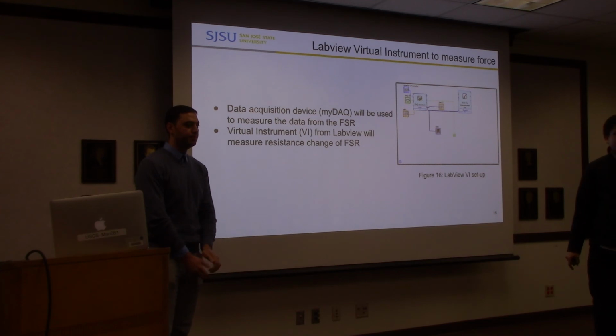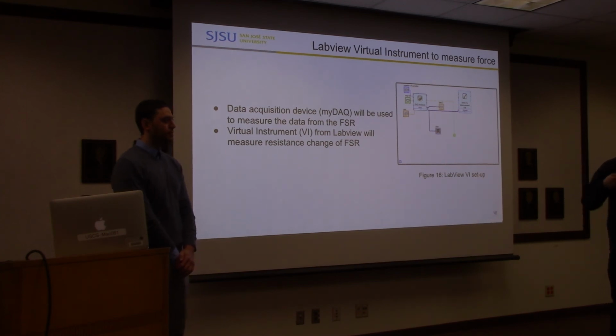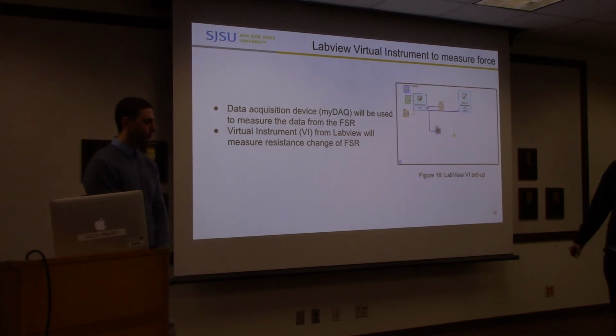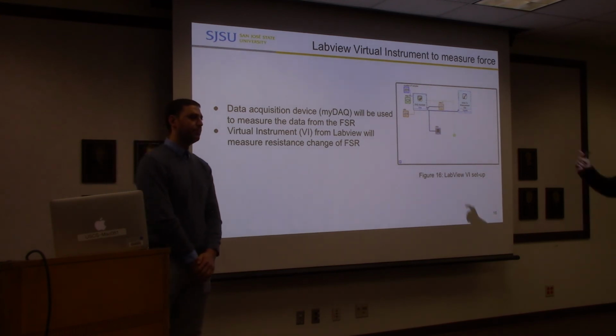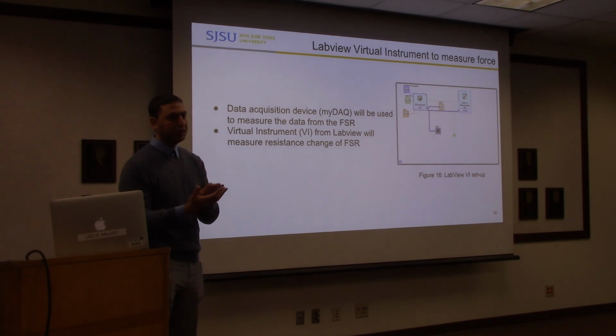And as we press the force on it, the resistance will have to change. So right now we're measuring the resistance. So later on, after this, we have to calibrate and match the resistance with certain known load. And from there, compare at our force load on the actual buckling fixture. Yeah, so the sensor just changed the current.